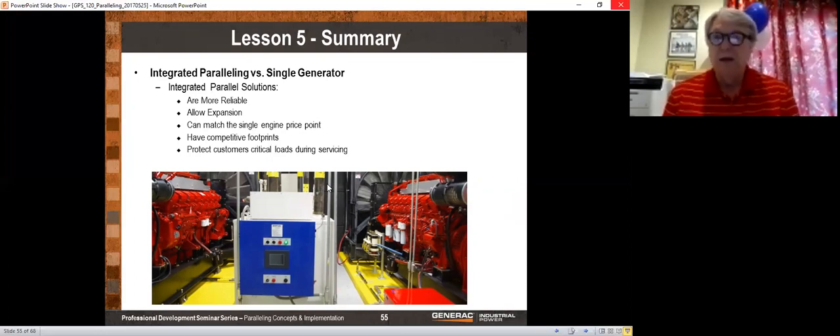utility power. And so if you have a generator and you can switch some loads to the generator during a peak time, then that's really easy and simple. And can you do peak shaving? Yeah, absolutely. And we do this all the time. It's becoming very popular that the utility will actually pay you to get off their system during peak times. And if you see peak shaving come up, you can do that. But the simple way to do it is to transfer some of your loads to the generator in order to